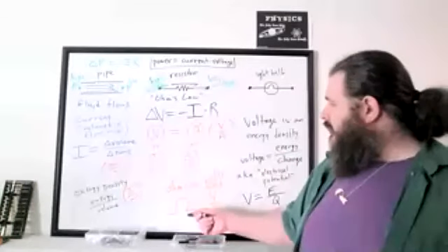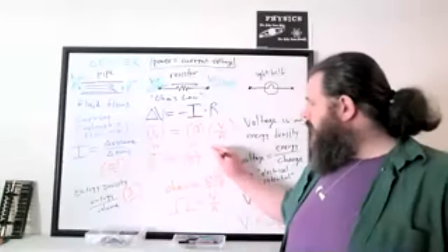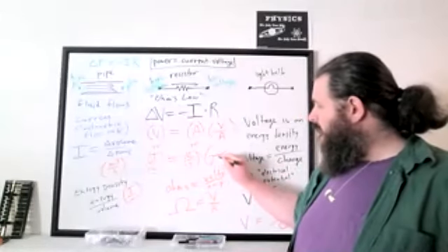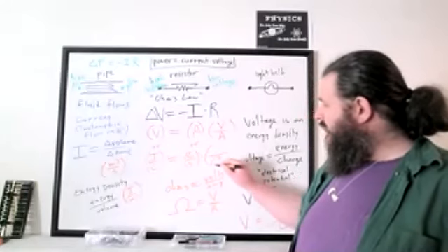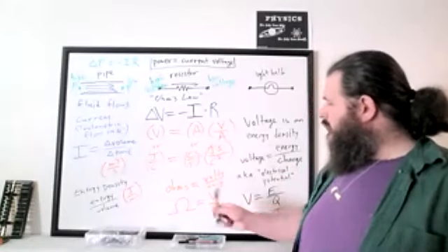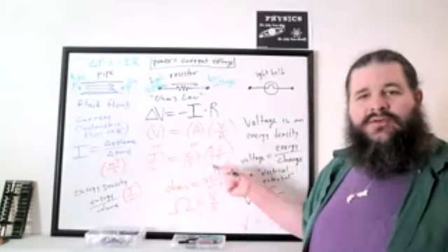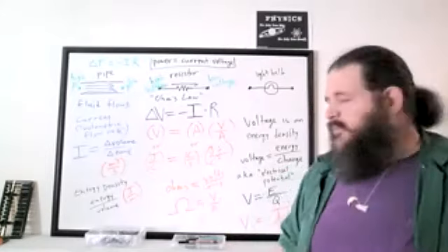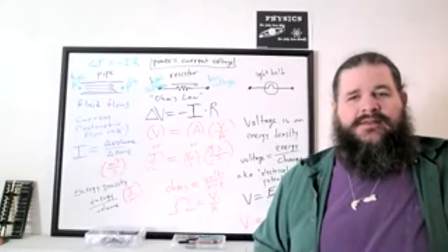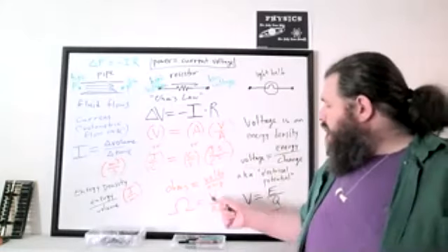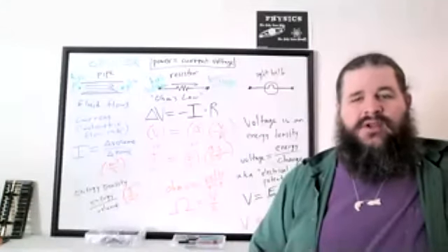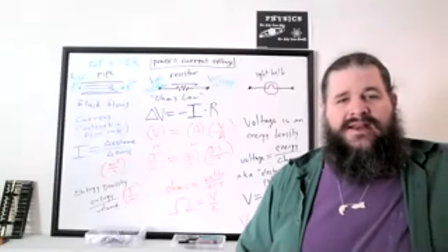You could also write that ohms in terms of all this other stuff. We need to cancel out coulombs and introduce another coulombs in the denominator, so we'll need coulombs squared. We got to get rid of seconds and introduce joules. So another way of writing ohms is joules seconds over coulombs squared, but usually it would just be written as volts over amps, because typically volts and amps are what we're actually combining it with. That means anytime you see ohms, you can replace it with volts over amps, and vice versa. Anytime you see volts over amps, you can replace it with ohms. They are just different ways of writing exactly the same thing.